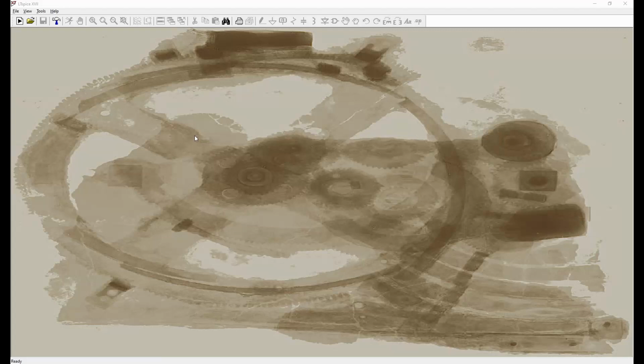So let's start off with the absolute most basic thing you can do in LTSpice. We're going to make a single voltage source and a single load and measure the values from that. For something simple like that, that doesn't have capacitors, doesn't have inductors, doesn't have other active components, the easiest method is to do a DC operating point analysis, which more or less just spits out the instantaneous calculations of what's happening right now. It has nothing to do with time.